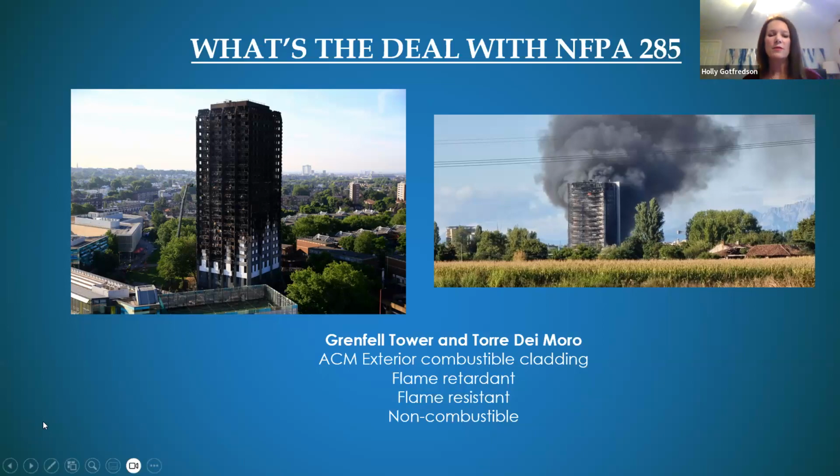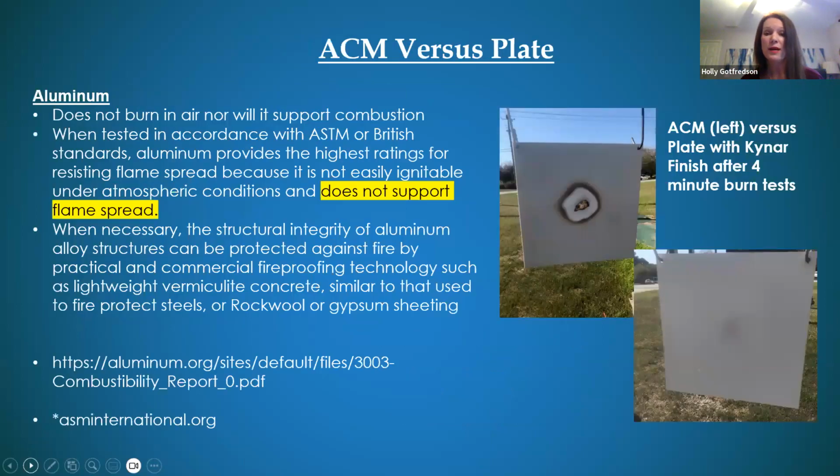Let's talk a little bit about this. There are some products that are flame retardant, some that are flame resistant, and non-combustible. Typically, ACM and MCM are going to have a core with two thin sheets of metal on either side. That core may be fire resistant or fire retardant for up to 30 minutes. But the core is a lot of times made with plastics and things that may not be recyclable upon decommissioning of that building.